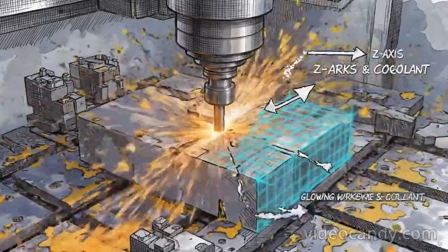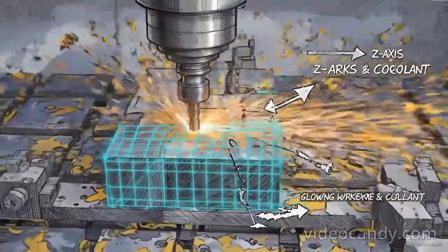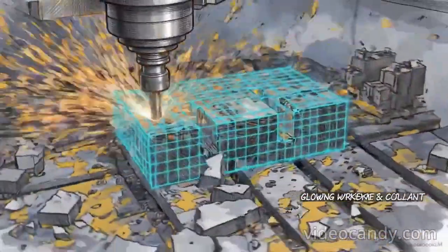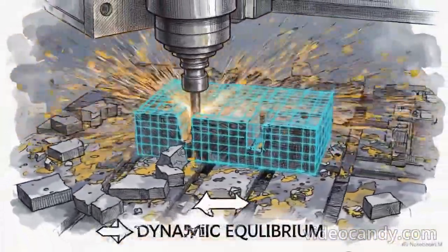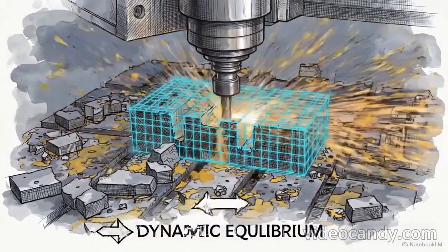Code is decoded by the MCU, amplified by the servo drives, translated into flawless linear motion, and strictly verified by linear encoders. Working together, they enforce a dimensional tolerance of 1/10,000th of an inch, even while carving through solid titanium. This ultimate manufacturing precision is a violent dynamic equilibrium, maintained microsecond by microsecond through the integration of digital code, high-speed electronics, and rigid mechanical engineering.